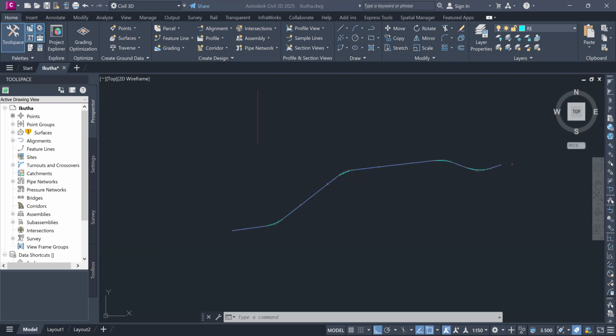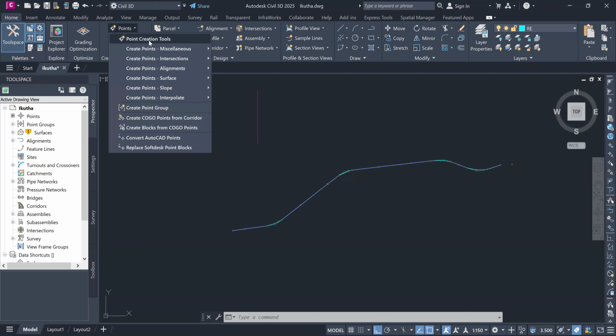The default setup for the coordinates is the PENZD, which is the points, eastings, northings, elevations, and the description. This is the order the points have to follow. Having edited the survey data to suit what you want, now you come to point